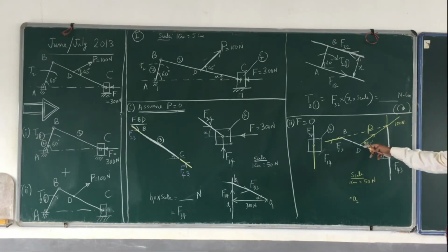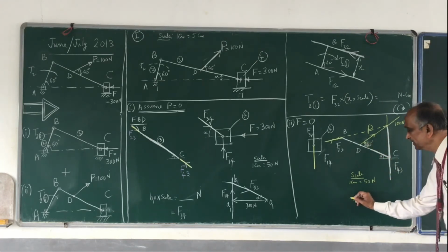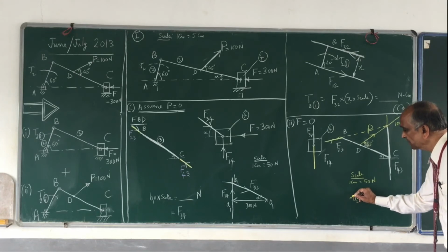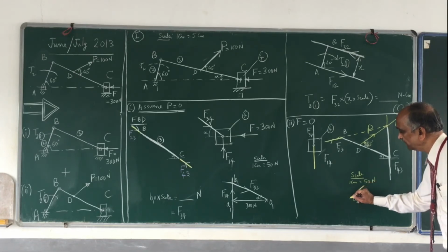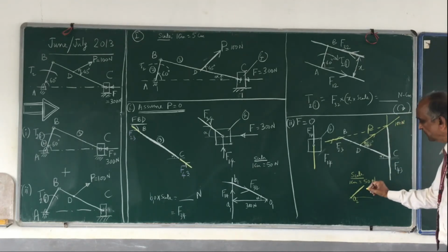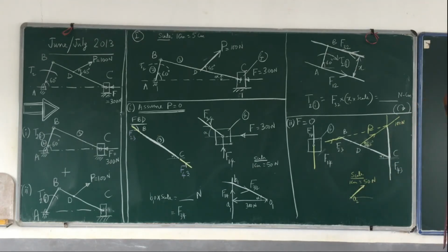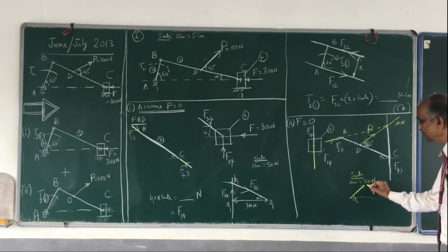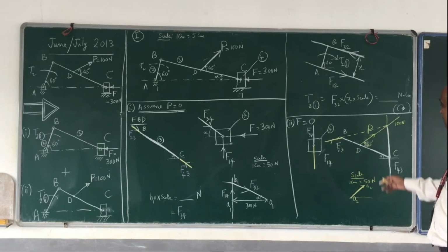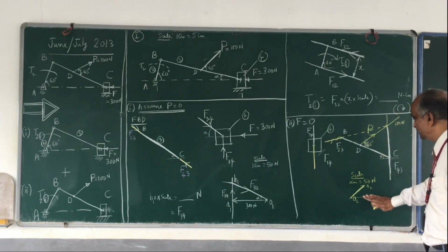The one which you know, please draw that first. What is that? 100 Newton I know. Where is it? You draw the horizontal line, measure 45 degrees and draw a line. How much length? Okay, 100 and scale 50. So draw what is called a 2 centimeter line and let me call this, say, A2. Now you draw any other force, the second force.